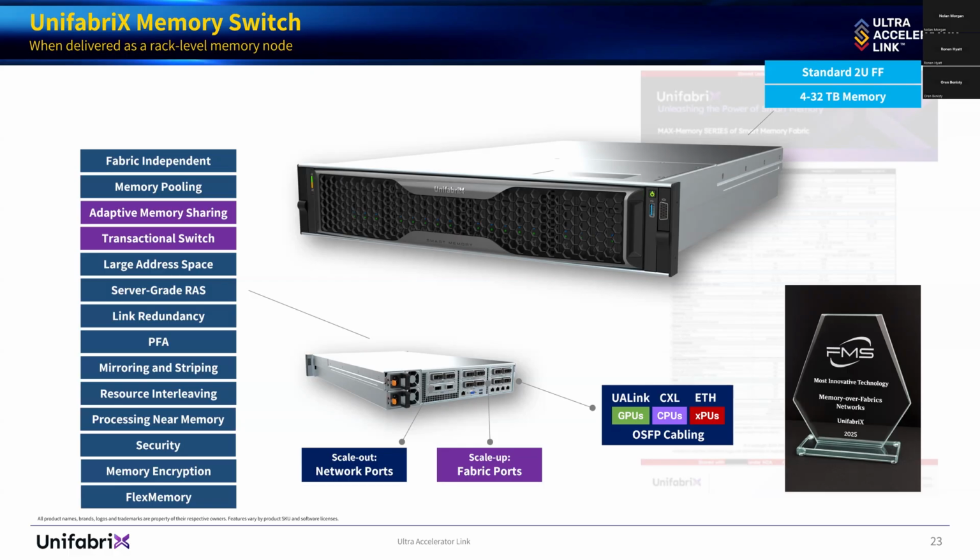Excellent. And on this slide, we have a question. What is PFA, that acronym there on the left side? Oh, it's predictive failure analysis. It means that you can detect an imminent failure of a memory component before it happens, before you're actually losing the data. And this is important because if you know how to do it well, you can migrate the data from this failing memory component before it becomes inaccessible, and move it to another place, and reprogram the memory footprint in a way that the consumer, the accelerator, a host, anybody who's using this memory doesn't even feel it.